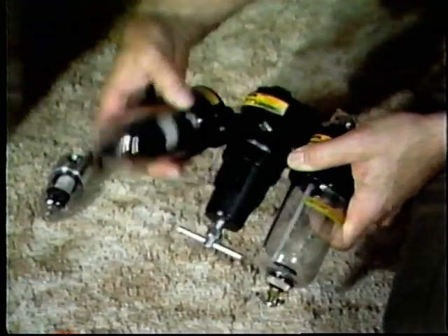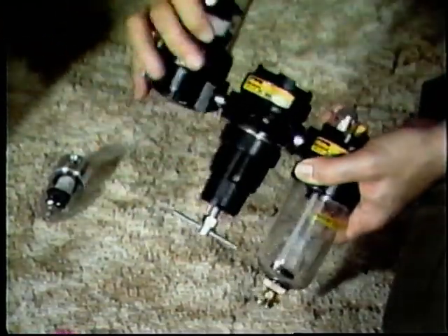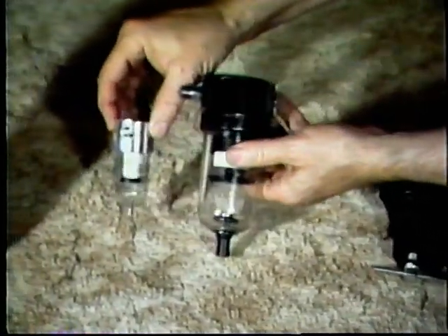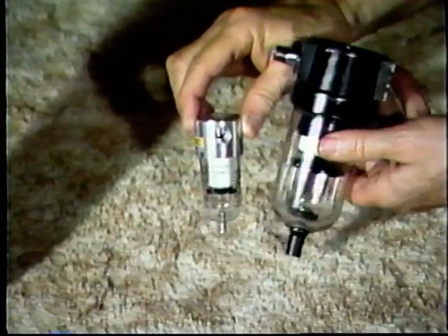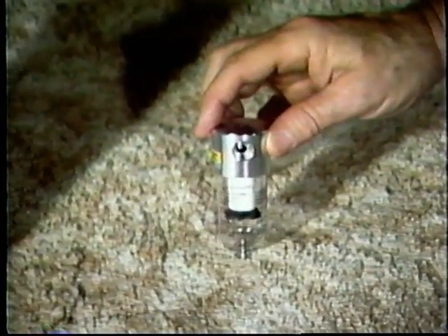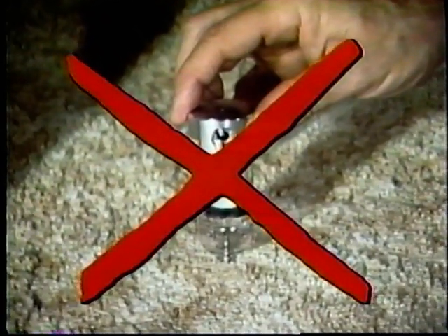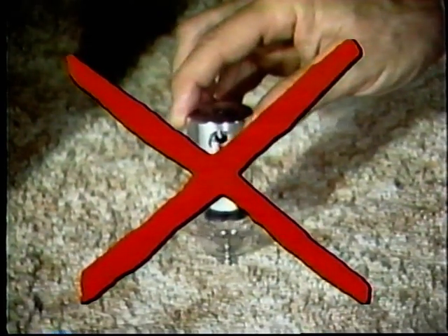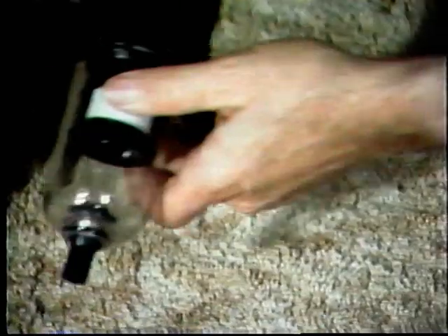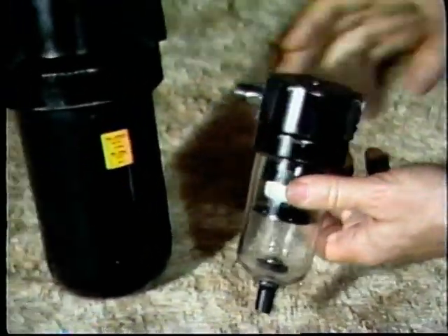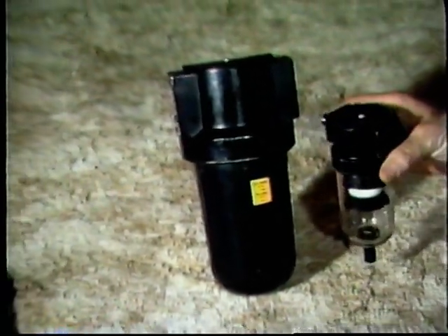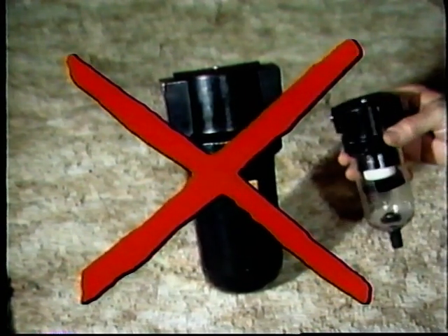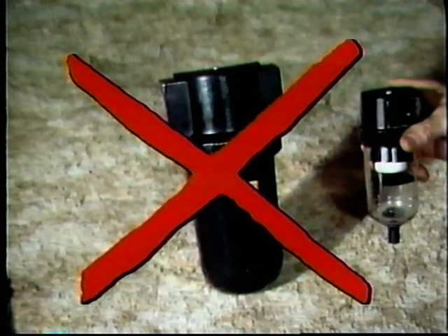When you are replacing an airline filter, make sure you replace it with one of the same flow capacity. Sized too small, the result will be a high initial pressure drop at the rated flow, and this can cause possible air starvation downstream. If you replace one with a filter that is too large, you can get a low swirling velocity inside the filter, and this means that contaminants won't separate out well.